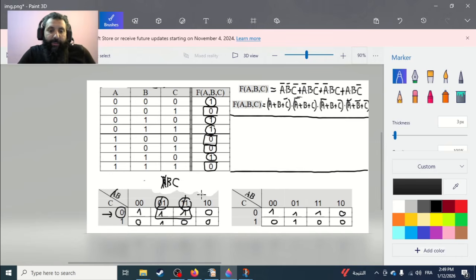After the elimination of variables, I have B equal to 1 and I have C equal to 0. In this case, I have to follow the same rule used here. The rule used on SOP said that I have to put a bar when the variable is equal to 0. In this case, I have C equal to 0, so I have to put the bar over the C. And this is the resulting term. I have to write it.